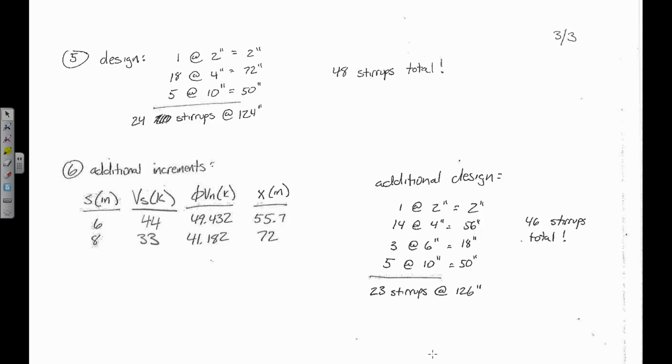What I'm going to do for a problem like this is place my support like here. So that's where the support condition begins. So this is 4 inches, this is 4 inches, this is 4 inches, and it goes on forever. But right here, that's 2 inches. Okay with that? The reason we start that first stirrup at 2 inches is to ensure that we have that stirrup spacing that goes across the support condition. So 2 inches is common, half of S is common. Well, either one is fine.